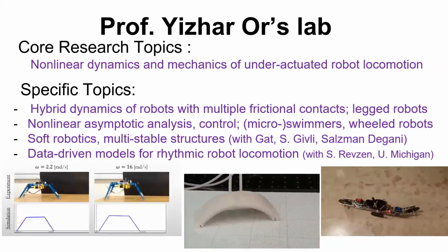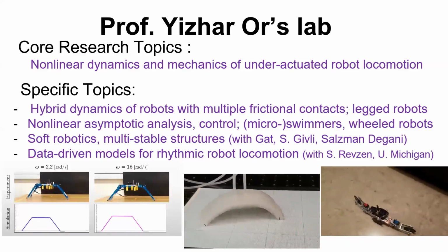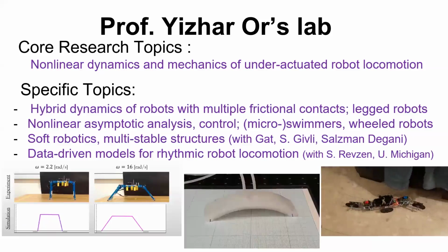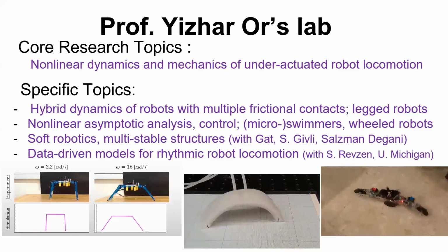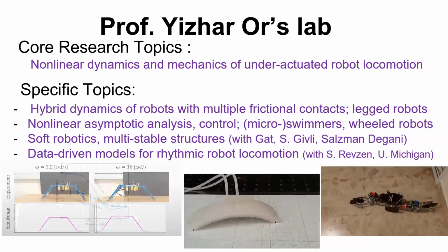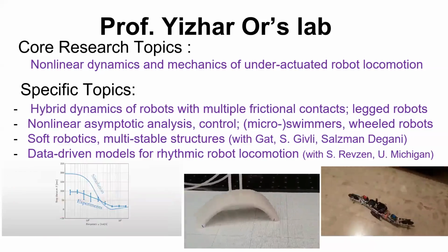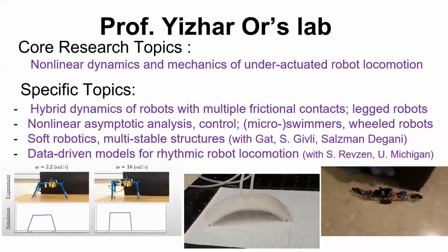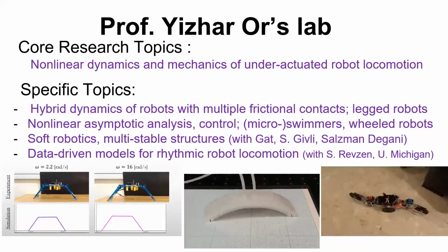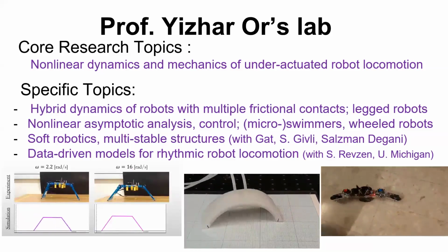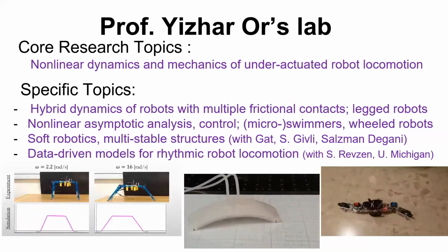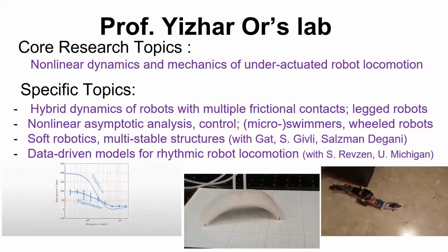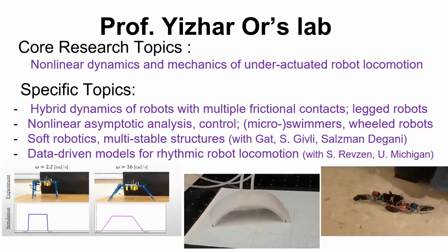Something like this. It's a differential equation. State equation. X is the state vector. If you studied anything with linear or nonlinear dynamical systems, it's a nonlinear dynamical control system because this is the vector of controls that we can control and describe them, and this can describe the motion of a robot, and this can describe forces or any actuation which we can try to minimize, and we are trying to drive this solution of this system to a desired trajectory, to some desired motion, and optimize the motion.